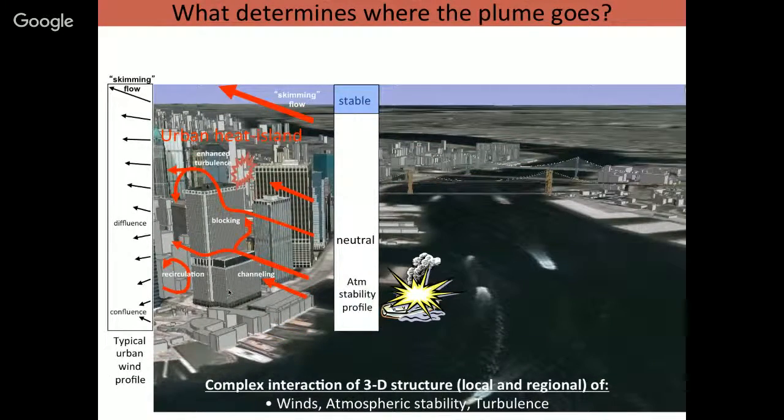But now imagine the winds are directed toward the city and you get all kinds of very complicated interactions of the contaminants with the urban environment. And some of the things we've seen are recirculations in the lee of buildings, pressure-driven transport up the side of a building. And so the contaminant gets drawn into an area of the boundary layer that's swifter, so that it could get transported many blocks downwind and get deposited in another entirely different neighborhood. We also see significant channeling down streets and penetration into surrounding areas away from where the immediate release occurred.